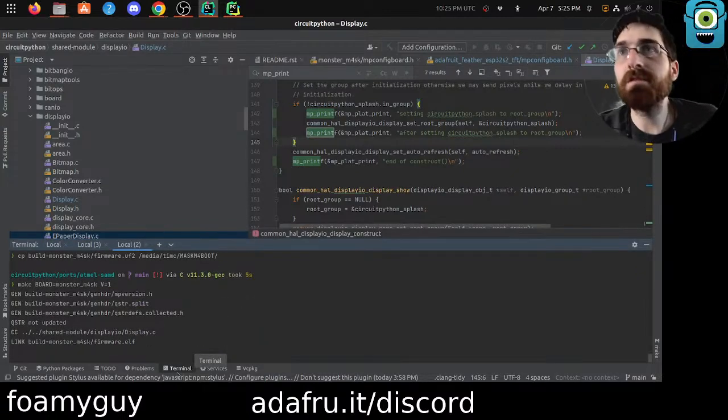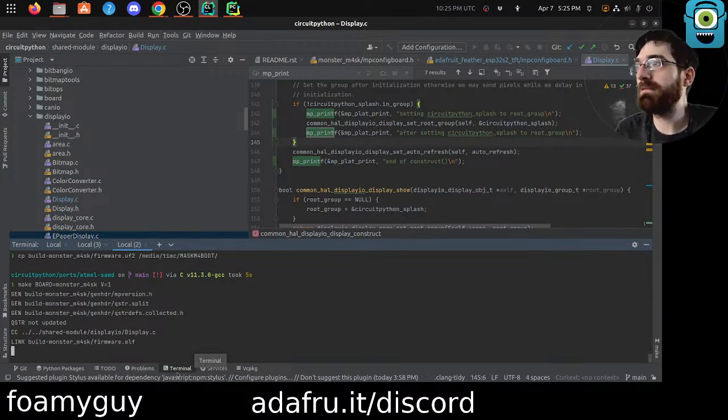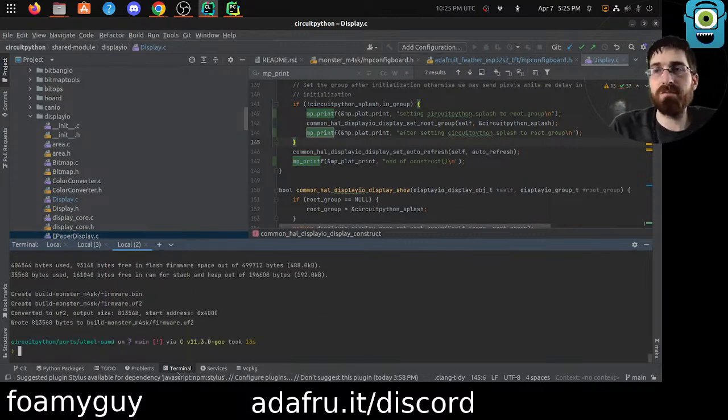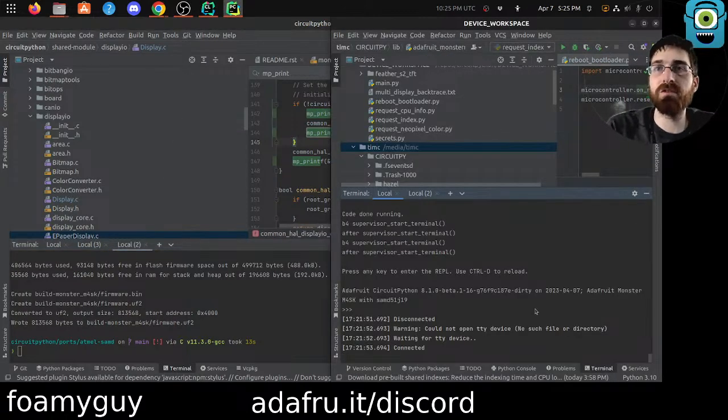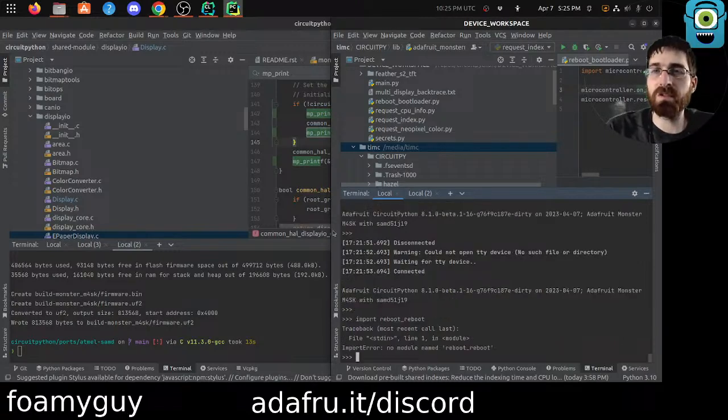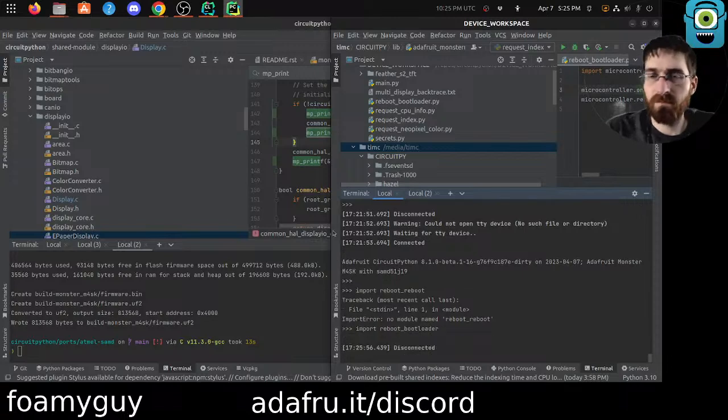Okay. If we get anything useful printed with those. It's so weird that it's quicker now. Why would it be quicker? Because before, we were explicitly able to press Control C even multiple times, get multiple REPL prompts, and only after I did a print H is when it actually hard faulted. But now I press Control C and we get a prompt, it starts like it's gonna work, but then hard crashes right away.